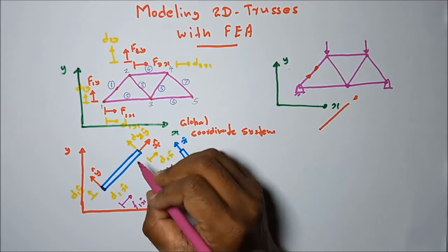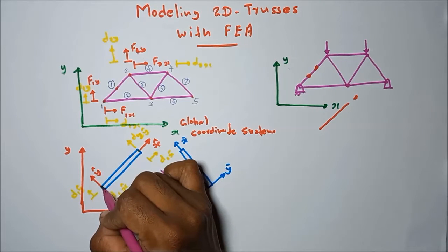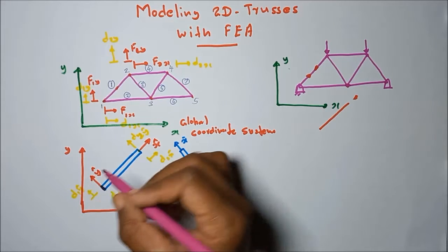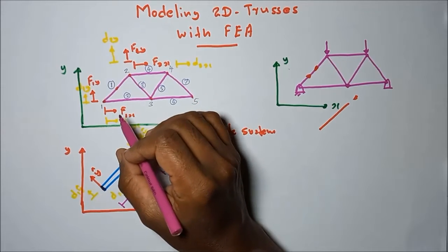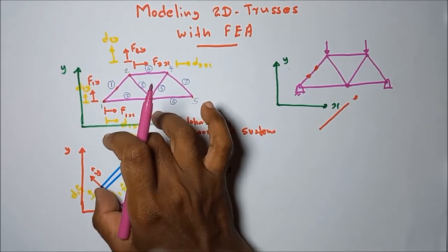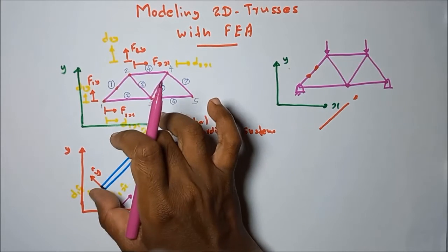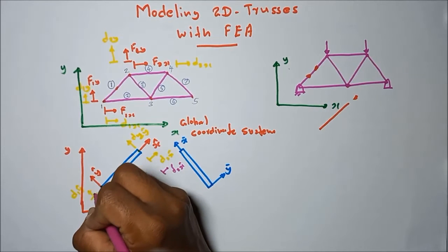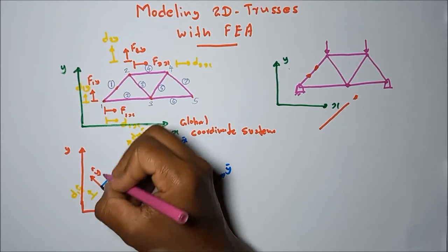Okay, then what can you say about the local force acting on the node 1 in a transverse direction, in the y hat direction? Actually, in a trusses structure, all the forces acting on the members are acting along the axial direction. There's no lateral forces. So that means in a lateral direction the force is equal to 0. Anyhow, we can mark that force in this kind of manner.